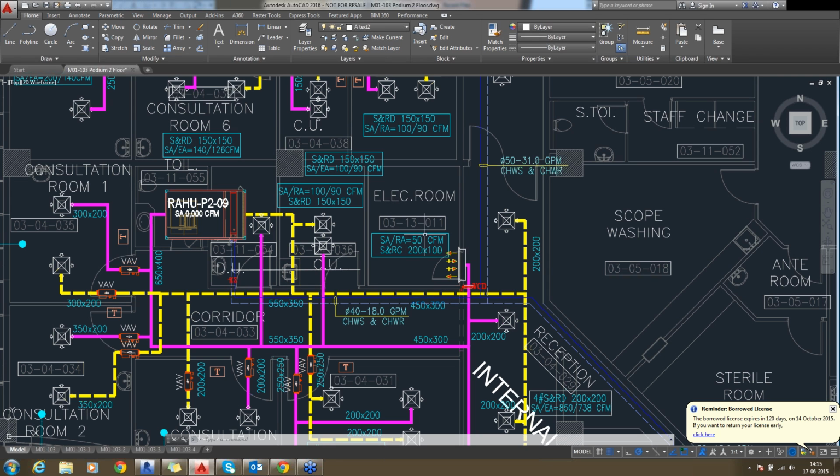Why don't we give it in between the rooms, like this room and this room? Because sometimes there is a possibility of leakage of conditioned air which is passing in the duct. So we will have a very small quantity of condensed water, but even so we should take care in electrical rooms to avoid short circuits.